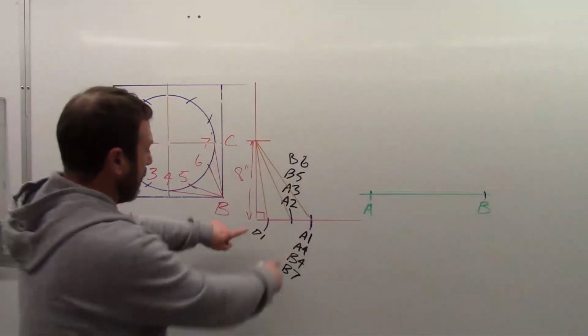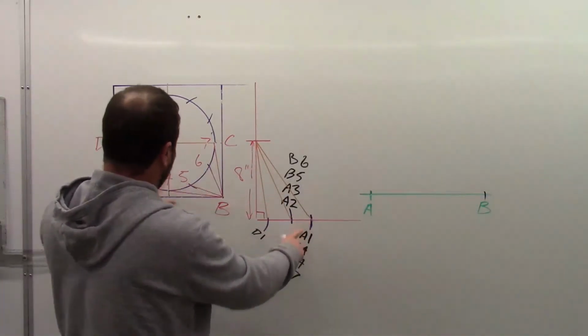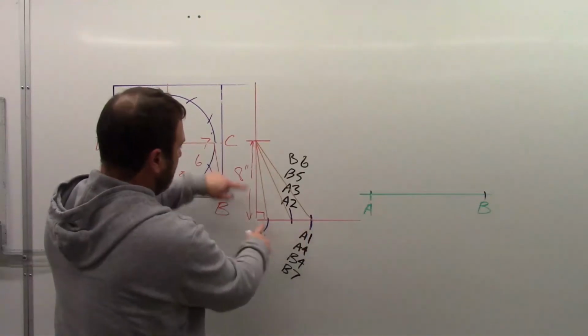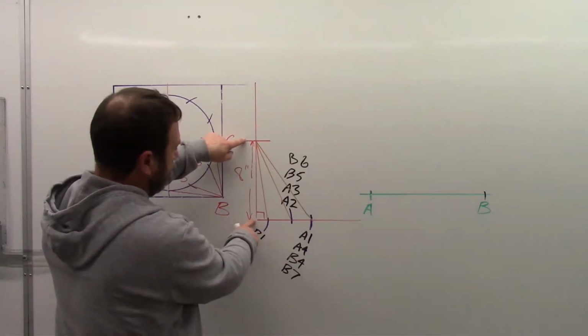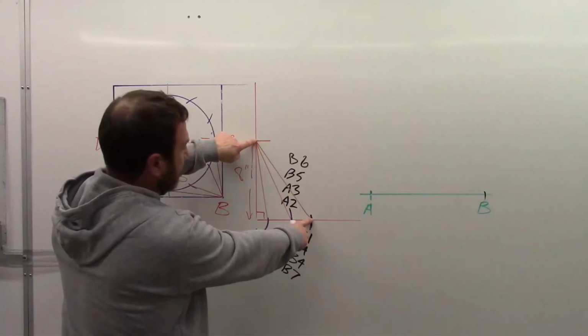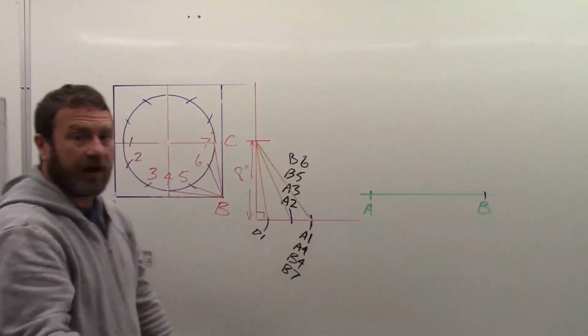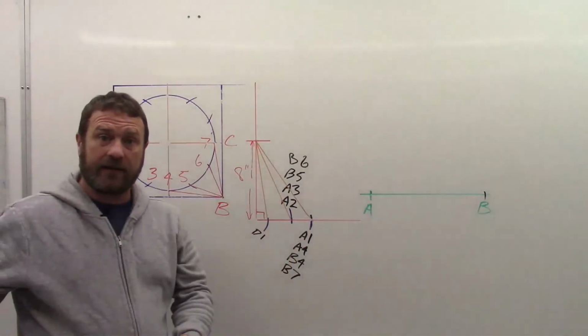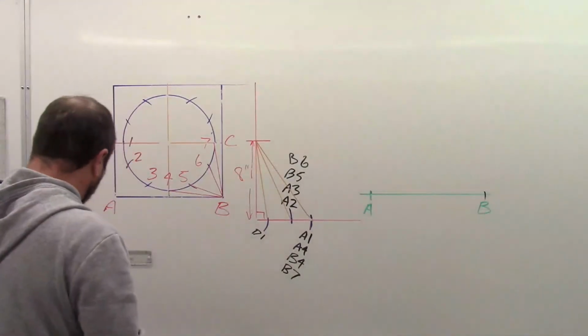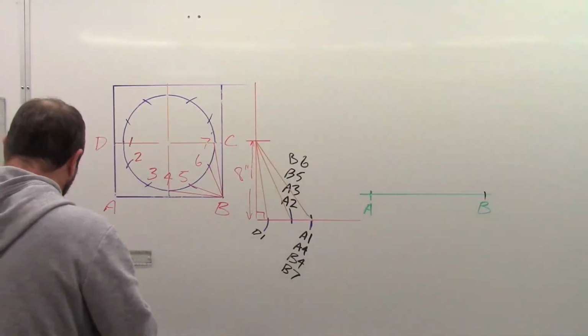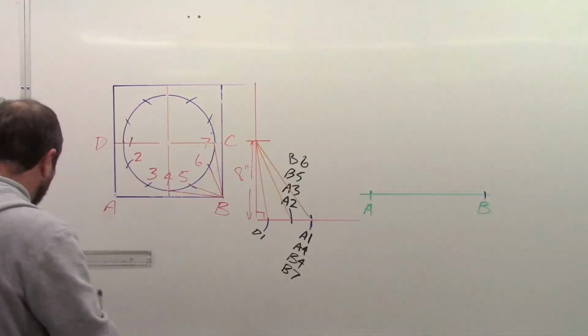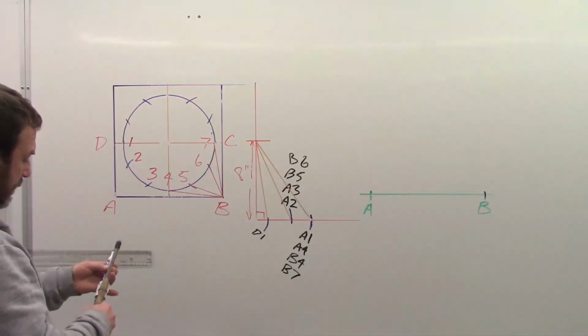So here's our plan length that we took from our plan view. 90 degrees to our vertical height now gives us the orange, which is our hypotenuse, and we know the hypotenuse in this process becomes our element line, our outside edge. Okay? So let's go ahead and start triangulating.